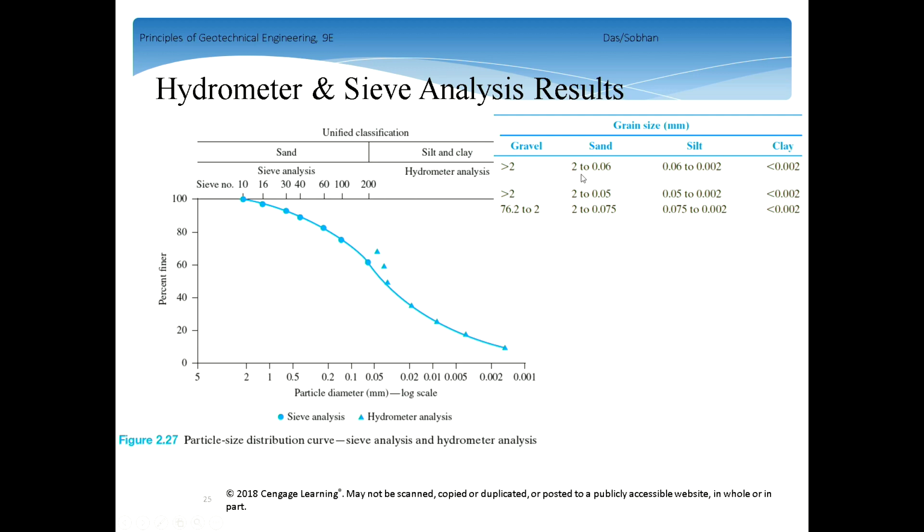If we follow this code to do the analysis, to calculate the percentage of clay, silt, and sand, then the clay is the particles at less than 0.002, right? So you find the 0.002 in the particle size distribution curve, and the y-axis is about in here, right? This is the percentage. This gives you the percentage of the clay, right? So the clay is about 12%.